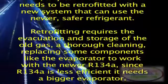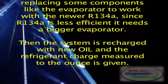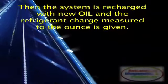Retrofitting requires the evacuation and storage of the old gas, a thorough cleaning, and replacing some components like the evaporator to work with the newer R134A. Since R134A is less efficient, it needs a bigger evaporator. Then the system is recharged with new oil and the refrigerant charge measured to the ounce is given.